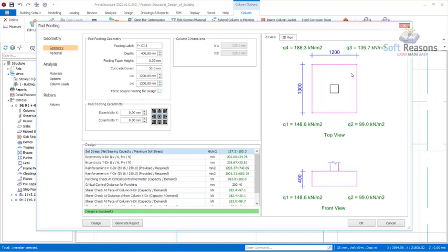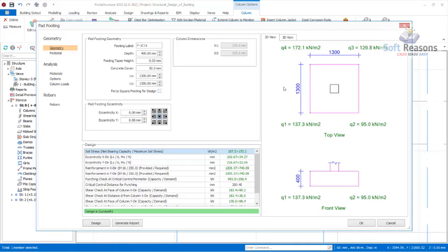What do we have here? The section selected for the footings is 1.2 by 3 right there. So we want to make it square, so we have to increase this to 1.3 by 1.3 successfully. Okay, so for the depth, the footing thickness, we'll change it to 350 right there and check if it will pass. Click on design right there. Okay, this has changed to 400.